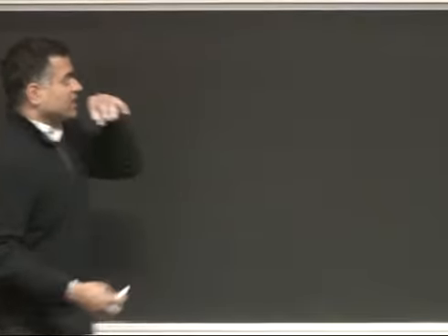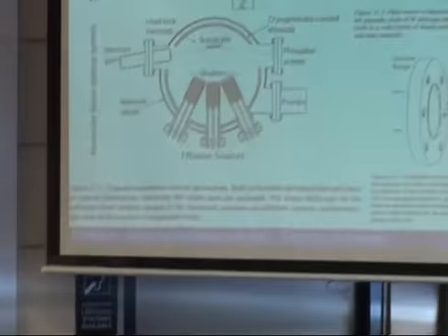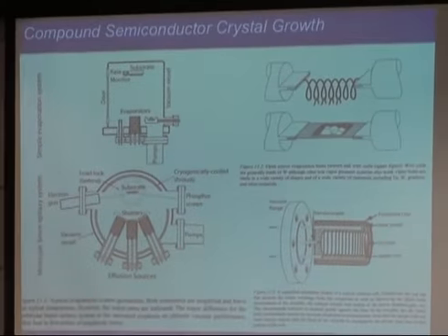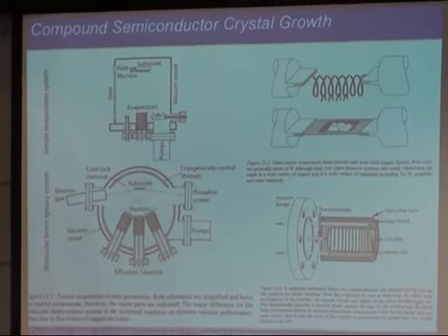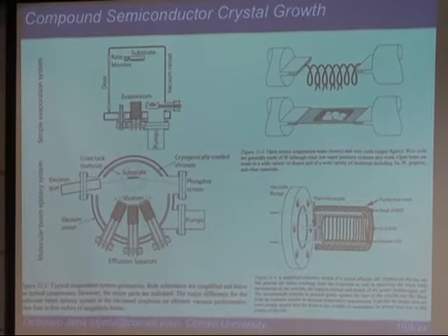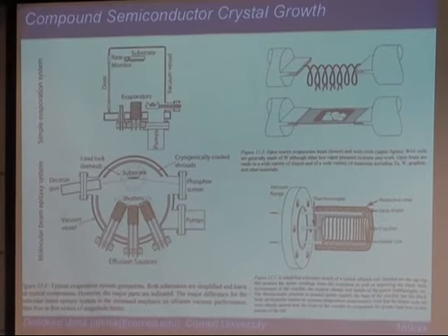So we'll look at this. I'm borrowing some stuff from chapter 11 in Rocket's book, and this is a chapter on physical vapor deposition. Physical vapor deposition as one method of growth of semiconductor crystals, so of semiconductor heterostructures, quantum wells, dots, all that sort of stuff. Okay? And again, the technique is actually kind of the simplest thing you can imagine. You want to grow gallium arsenide. So you need gallium, you need arsenic, right?